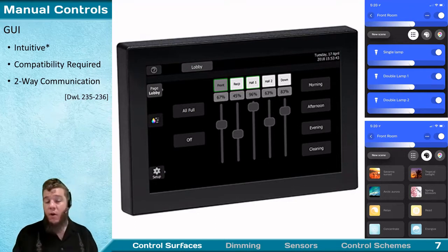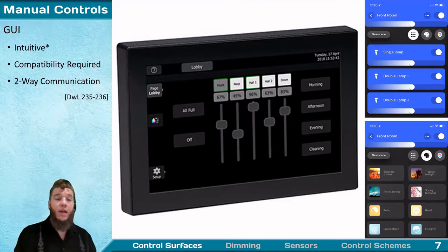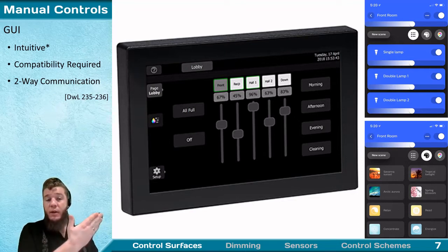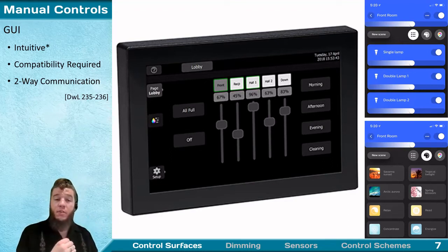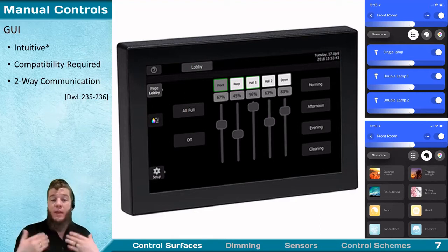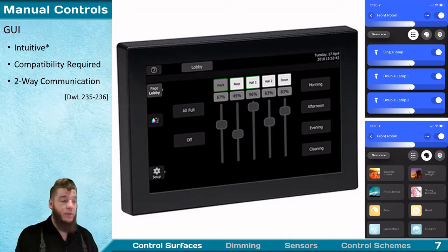Of course, they are also going to be backed up by some sort of microcontroller, almost always utilizing a digital control signal. Again, you're going to have that concealed configuration layer, maybe in the form of a companion app, but also in the case of this device right here, which is actually a wall-mounted graphical control surface, you can see the setup button, and you would just password protect that in an architectural setting so that you're locking out your average user and restricting that to the building management.